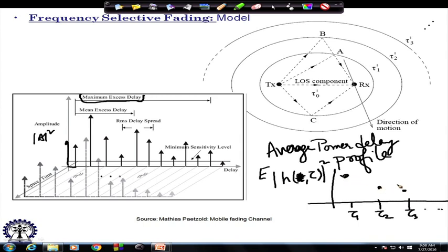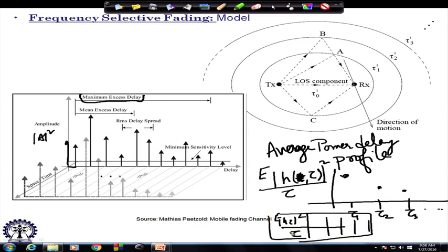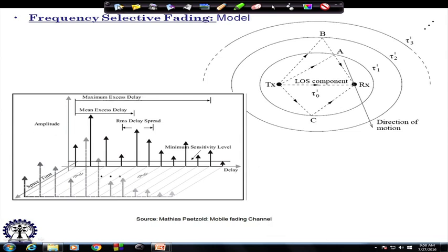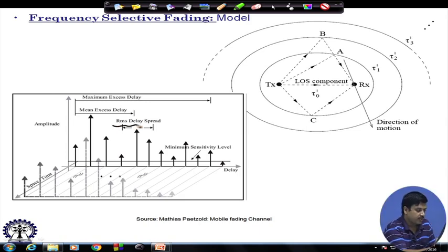We will look at certain power delay profiles. Along with this, now this is not a very easy description, because you need to describe so many things. You need to describe this versus the time. So, basically you will be giving this tau axis, tau table and E of h tau mod squared. So, you will be giving these values through which we will be describing the power delay profile. Now, beyond that we should be able to describe it in a much easier fashion, and it is described in an easier fashion by using certain other single variables. So, one of them is the RMS delay spread.